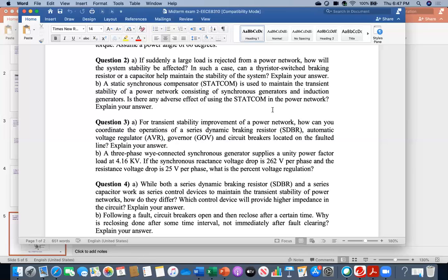You are continuously switching that STATCOM on and off with the help of power electronics, and consequently the impact will go until the shaft system. Therefore, there can be some shaft oscillation, and sometimes it has been seen in real practice. If it is too much, there are examples of shaft damage, where the shaft section got damaged.